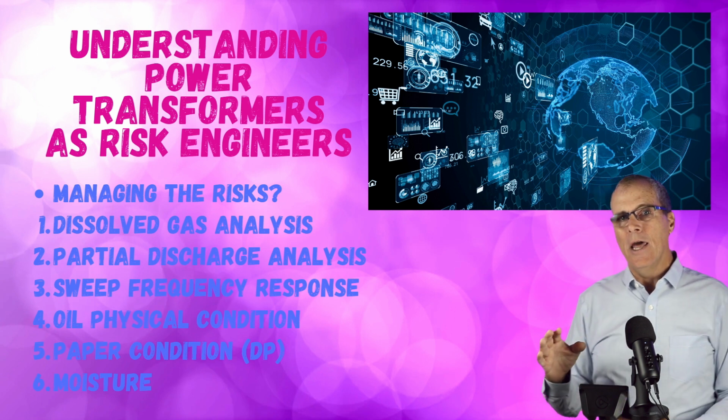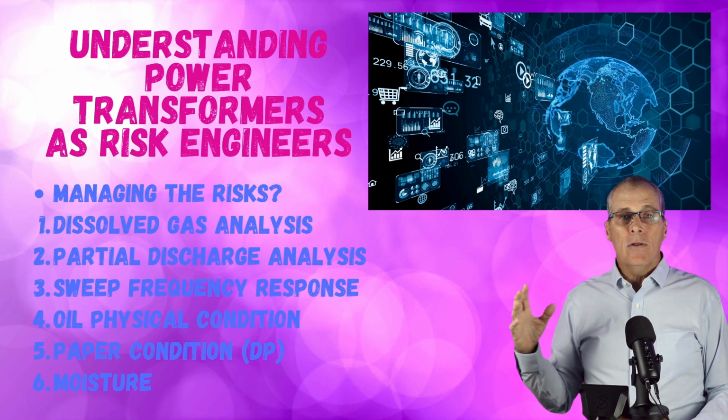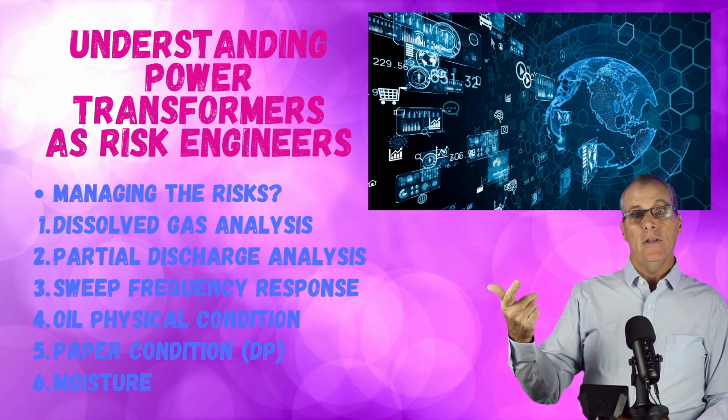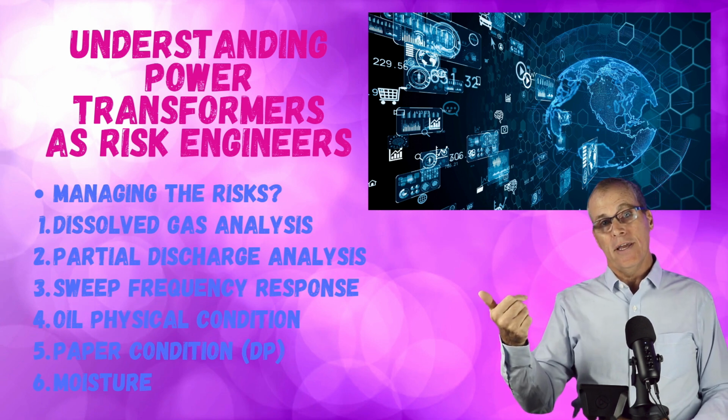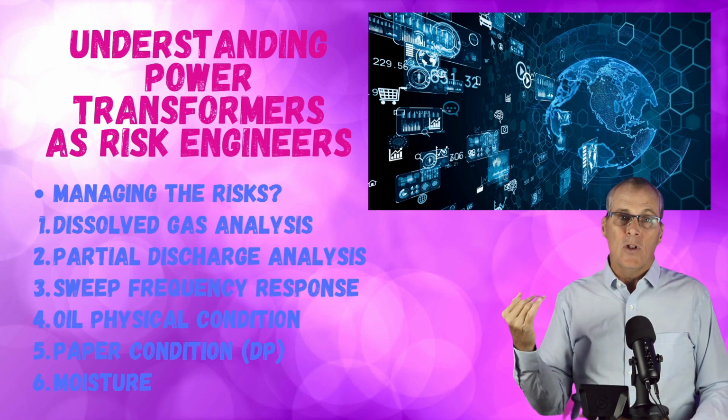You're not going to need to know what gas is attributed to what fault, because remember, the only things that mess up a transformer are arcing, right? Or losing the insulation, right? That leads to arcing and overheating because the insulation's failed. So we're going to look for those things.